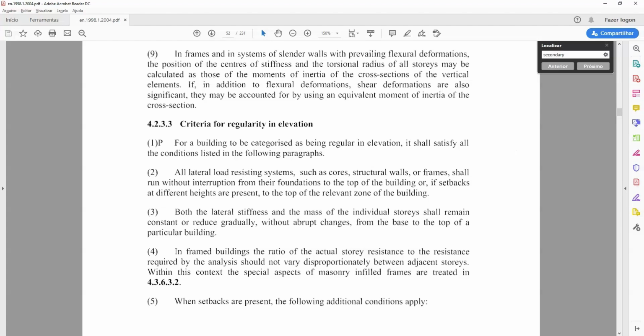The third important aspect is that there should not be changes in the overstrength of the building at each story between adjacent floors. The elements we design at each story will certainly have a certain overstrength factor relative to the design forces, and the requirement is that we do not have overly overstrength elements on floors that are adjacent, ensuring this factor is not wildly different between adjacent levels.